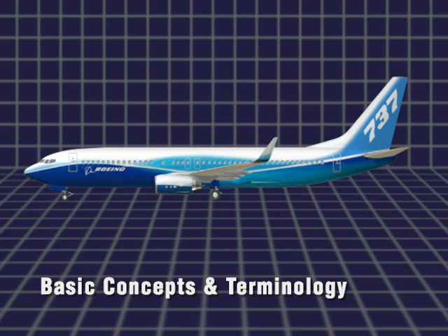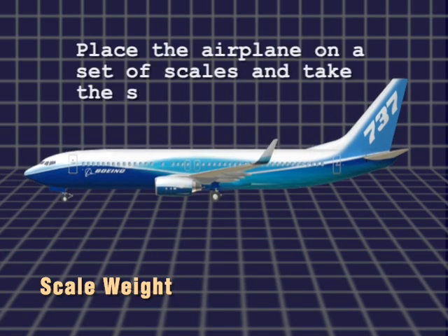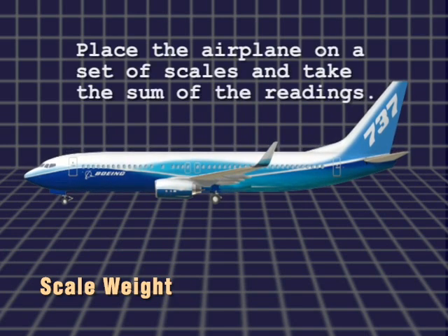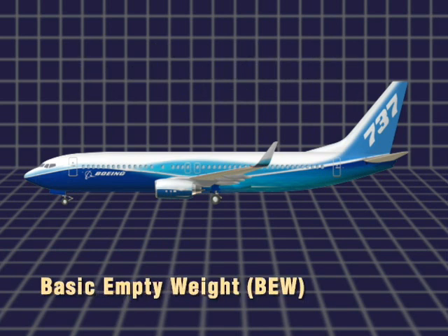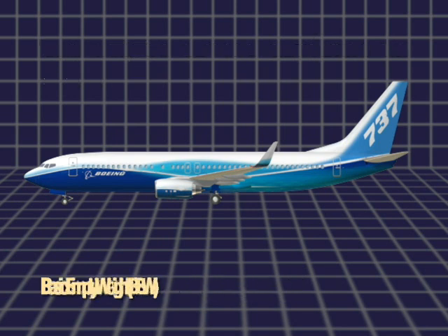Here we are taking an example of a 737-700. The same general procedure is valid for all models. Major exceptions will be noted appropriately. The process we are going to learn is deceptively simple: putting the airplane on a set of scales and adding their readings will tell you what the airplane weighs. But getting accurate and reliable readings and determining accurate CG involves strict adherence to a consistent, reliable, and detailed process.